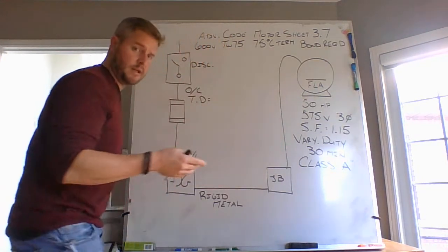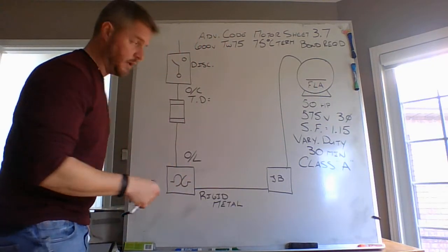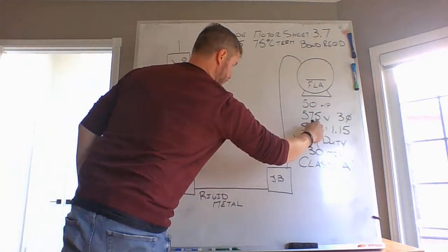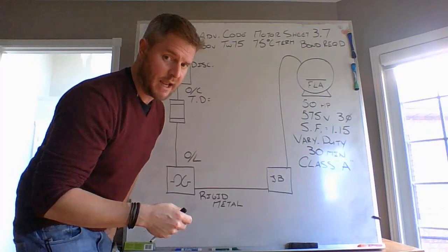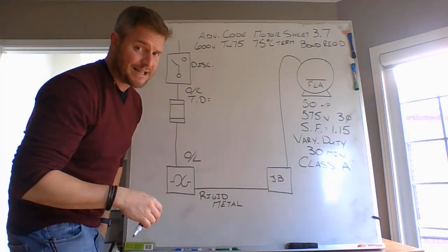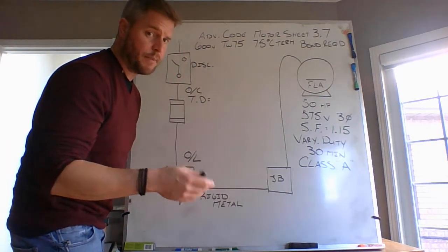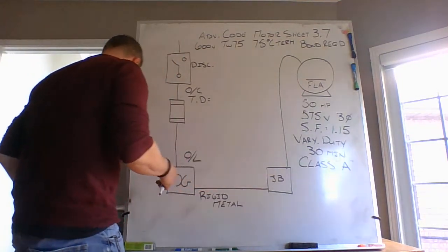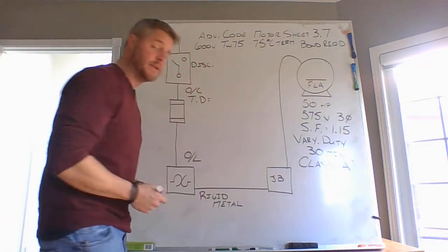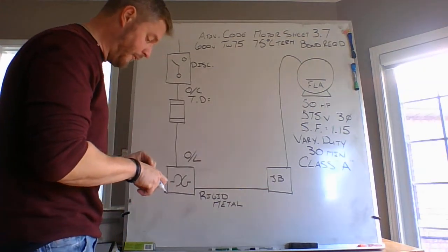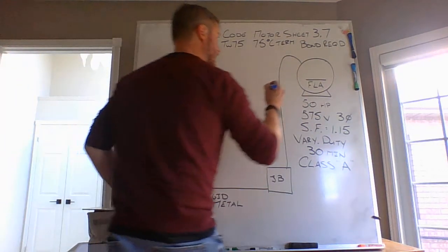So if you read table 44 incorrectly for this 3-phase 600 volt motor, and you come up with a weird value of like 70 amps, I'd second guess that, because you're about 1 amp per horsepower. If you came up with a different value, like 52 amps, which you'll find from table 44, 52 amps,